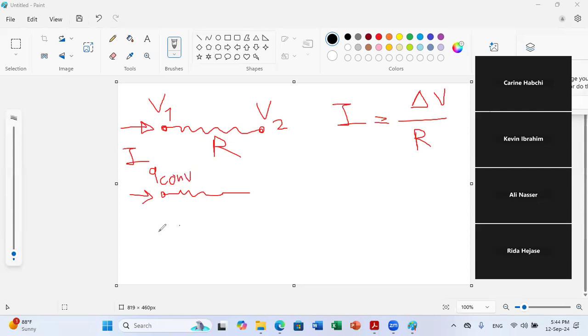And in parallel, because I am adding two fluxes, you know that in the case of electricity, when you have resistances in parallel, you add the intensities. And here it's the same. If heat transfer is divided into two parts, it's equivalent to two heat rates coming in parallel.